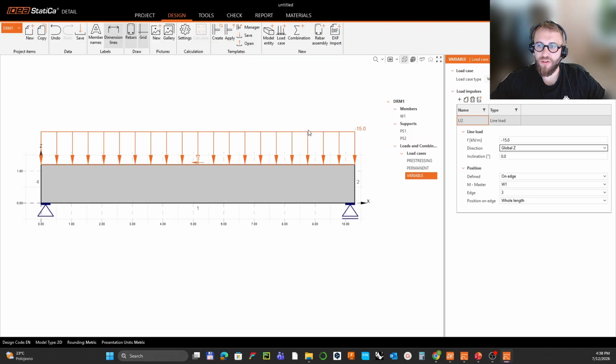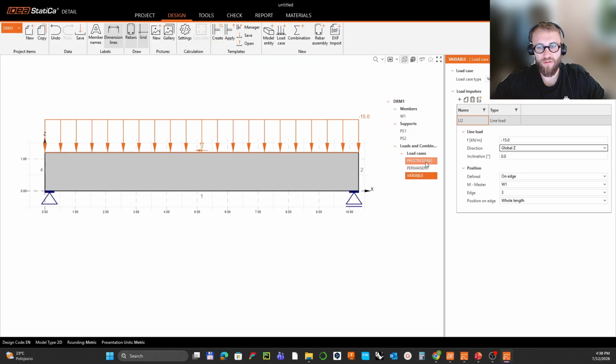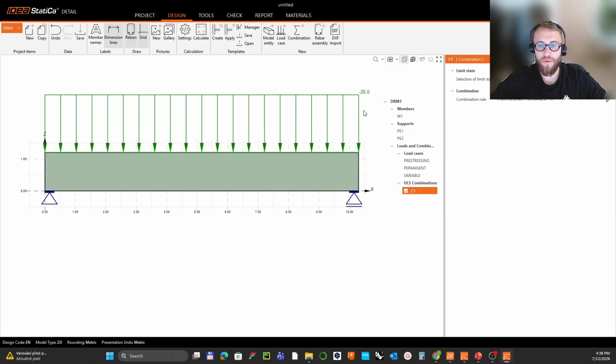At this point I have all three load cases that I need to cluster into the combinations, because the solution is based on a combination approach, and running and post-processing the results for the combinations. So at first I will prepare the C1 combination, and I will rename it. This is pre-stressing plus self-weight. Yeah, we'll just call it like that.